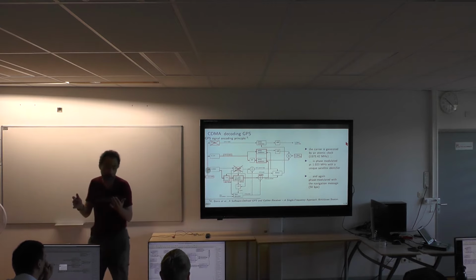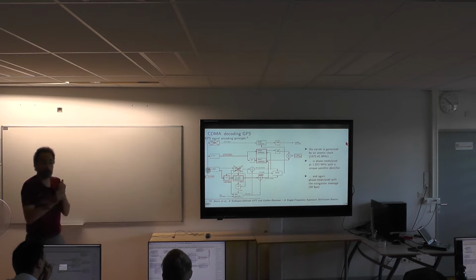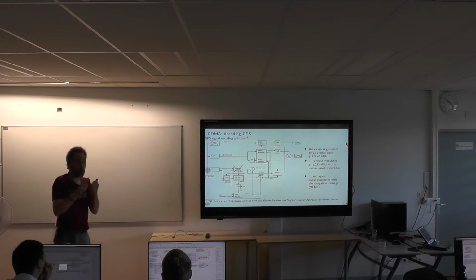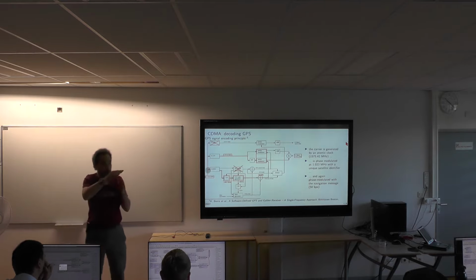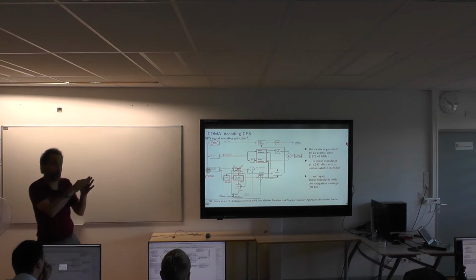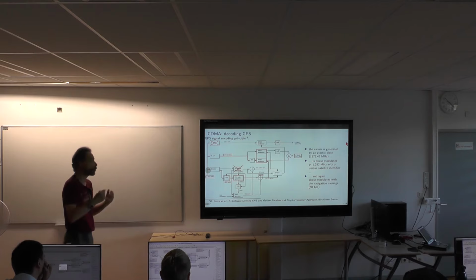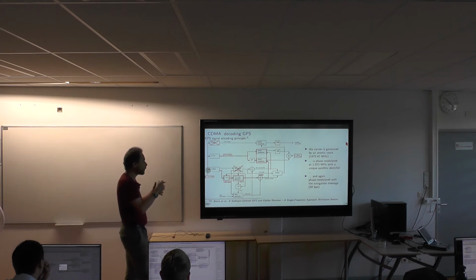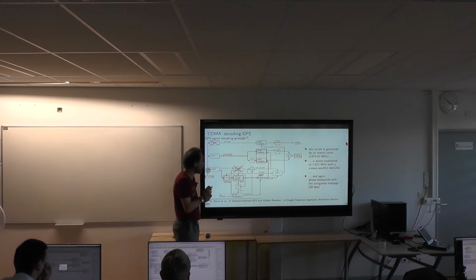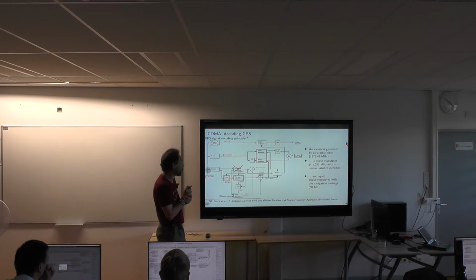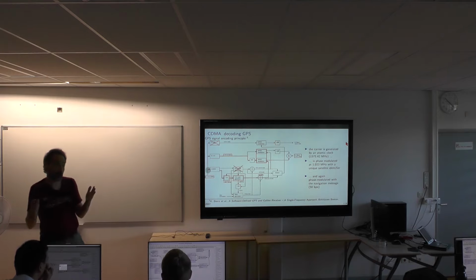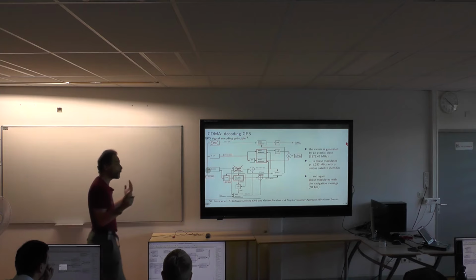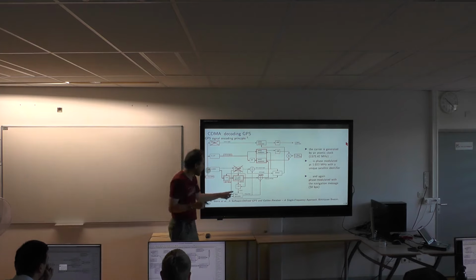The payload is, for example, the time offset between the satellite clock and GPS time. You never steer an atomic clock, you let it drift, because this is a very reproducible drift, so you let it run by itself, and you document to the user the constant and linear offset of the clock with respect to your receiver. And you need to have the ephemeris to position the satellite in space, and this is all information that is broadcast in the data payload.